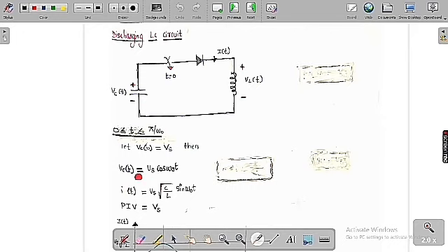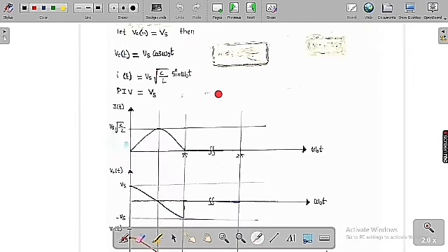So we know the value of the capacitor voltage and the current in the inductor. You can see clearly that when the diode is on, both the voltages are always equal. Therefore, VL of t is equal to Vc of t, so the diode is on. Omega naught is equal to 1 by under root of LC. You can see clearly here the sign is positive only for 0 to pi. Only for 0 to pi the current is positive. So if you draw this expression, all these are going to hold only for omega t lying between 0 and pi, or simply for 0 less than or equal to t less than or equal to pi by omega naught. All these equations hold in that interval.